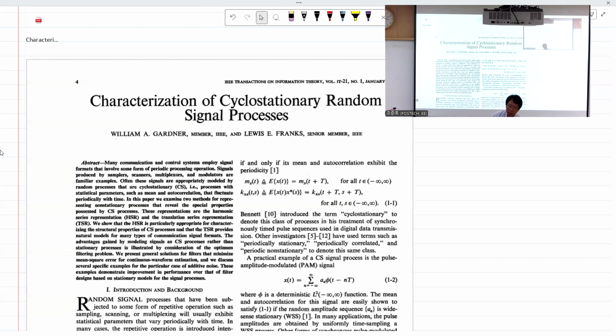Consider that you have an axis rotating very fast. Then you have some defect. Then you will see some periodic bump, right? But your sensing system may have some noise. And your observation looks like cyclostationary random process. So interestingly, vibrations are the key words related to cyclostationarity these days, but still sometimes I see some communications and signal processing papers talking about that. Anyway, so let me go back and continue.